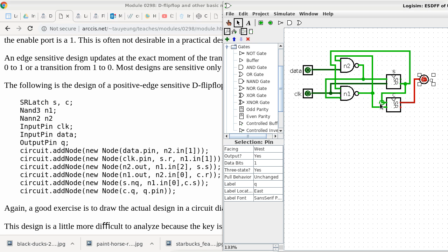It has a little error here because, remember, we have problems when both input pins are ones. There's no previous state to remember. So this particular SR latch is going like, well, you're asking me to maintain the current state, but I do not have a current state to maintain. So that's why it's not happy about it.